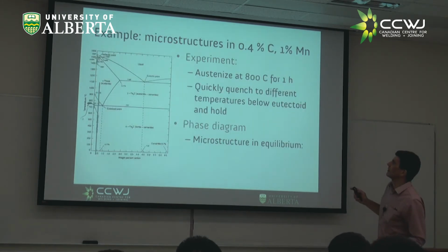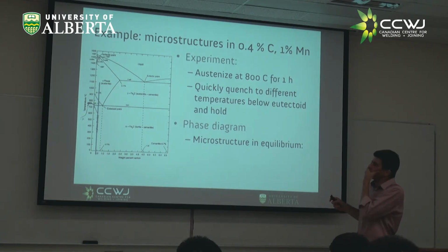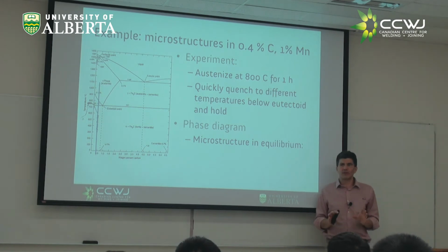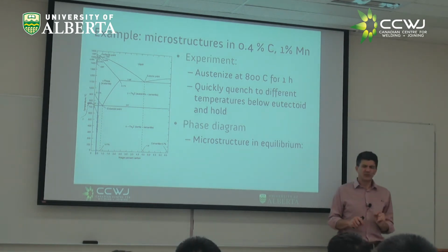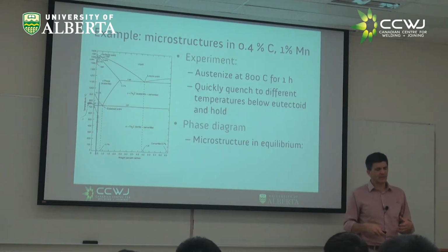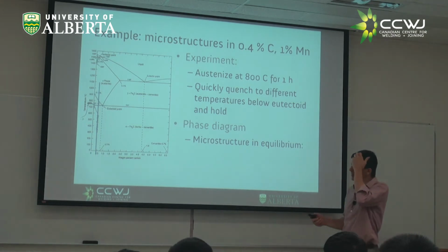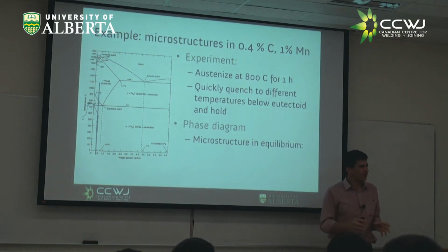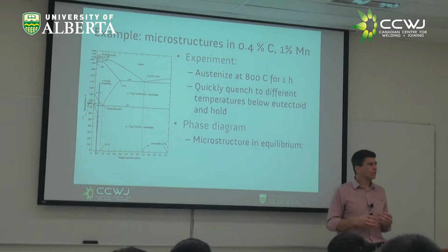All right. So let's talk now about something closer to home, right? A 1040 steel. Again, you seldom want to weld steels that have 0.4% carbon, right? They can form martensite, they can crack. You need to preheat, lots of things. So this is a more reasonable steel to talk about, but there will be different features.